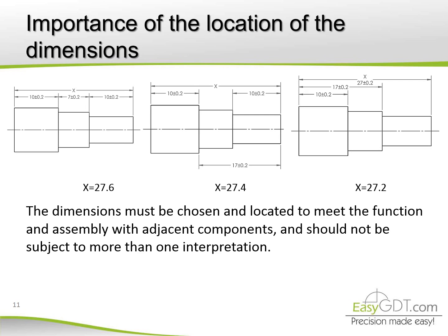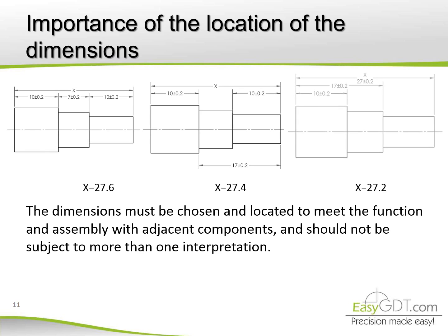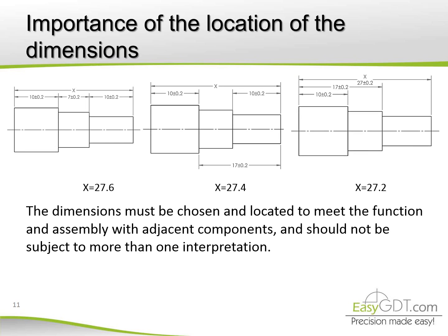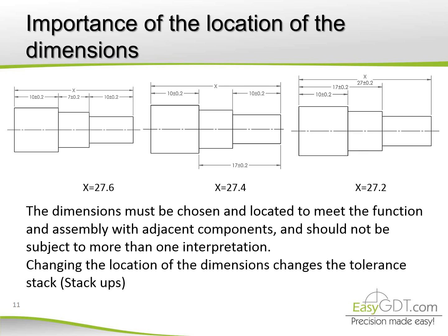In the first case, the individual dimension is the most important. In the third case, each dimension is more important in relation to the base. We have seen how changing the location of the dimensions changes the tolerance stack, also known as stack-ups.